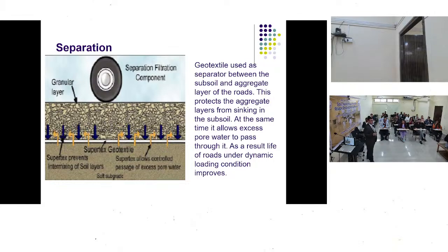And this is a problem which we might be facing a lot at times. What happens is that suppose you have a particular road and, because of the infiltration of water into the embankment of the road, one fine morning you find a pothole has started, and once the pothole starts, that is the initiation of the failure of the road. So once the pothole starts, what happens? Again, the traffic is going on.